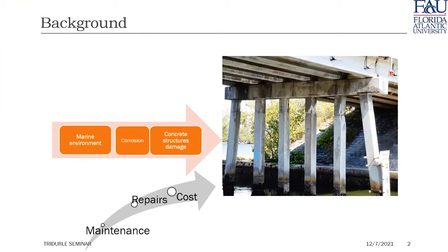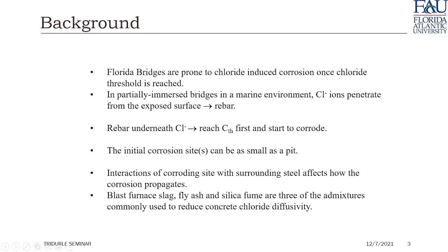Dr. Criswell, in a previous presentation, just spoke about the importance of tracking corrosion and damage in concrete in the marine environment, which can result in major costs associated with repair and maintenance. What happens is that, for the most part, chlorides reach the rebar in the reinforced concrete, and after a certain point, corrosion starts, and that causes the concrete to crack.